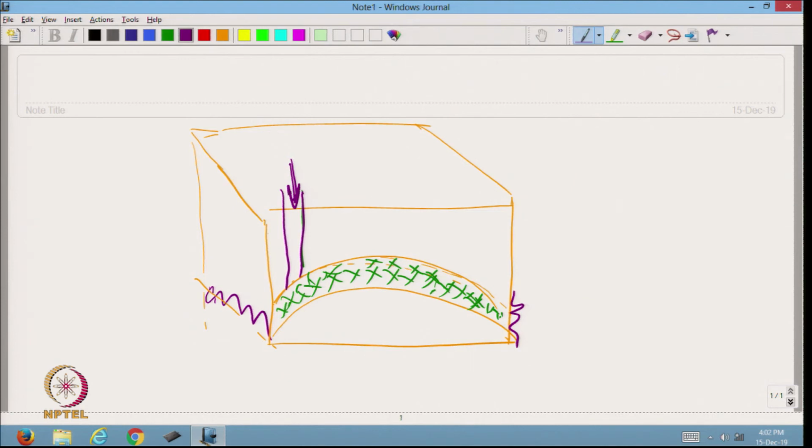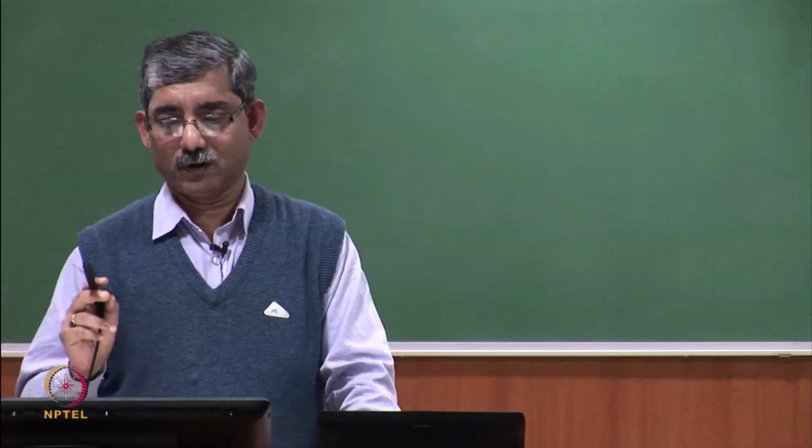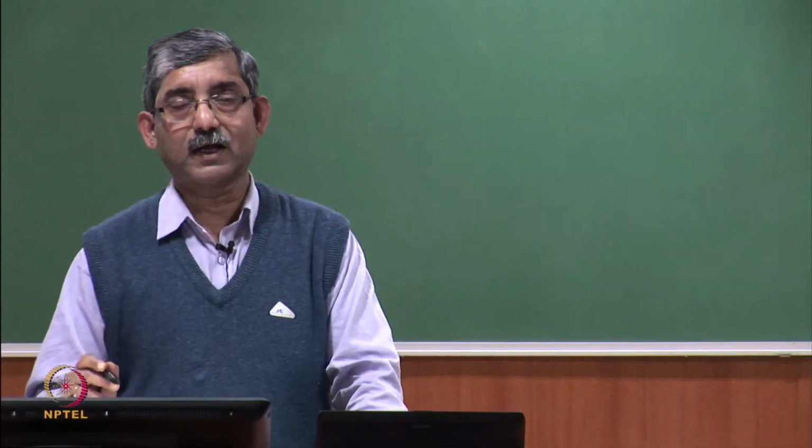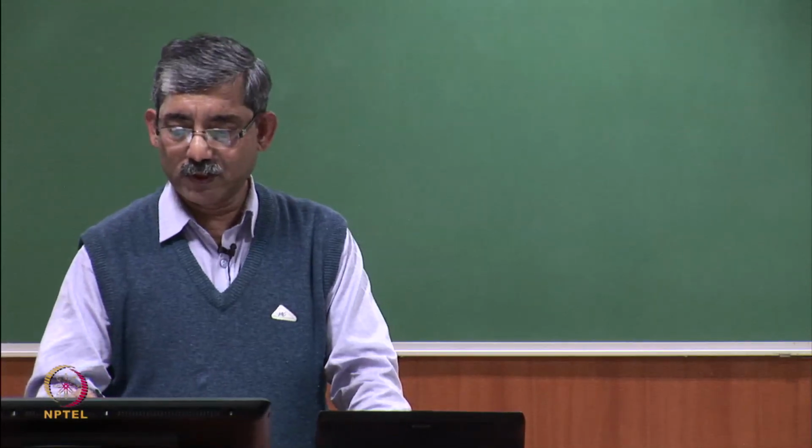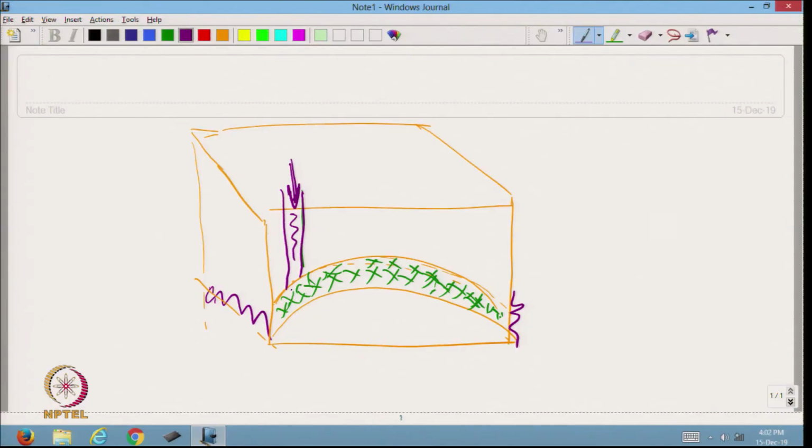And in this system only thermoset resin can be used. Due to its low viscosity, it will penetrate into the structure of the textile material, and after curing, this is one side of the mold, this is a male mold, and if you see, it is a female mold.